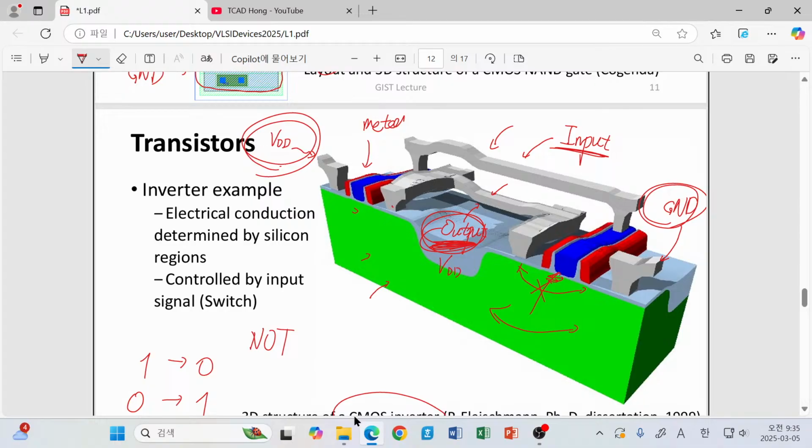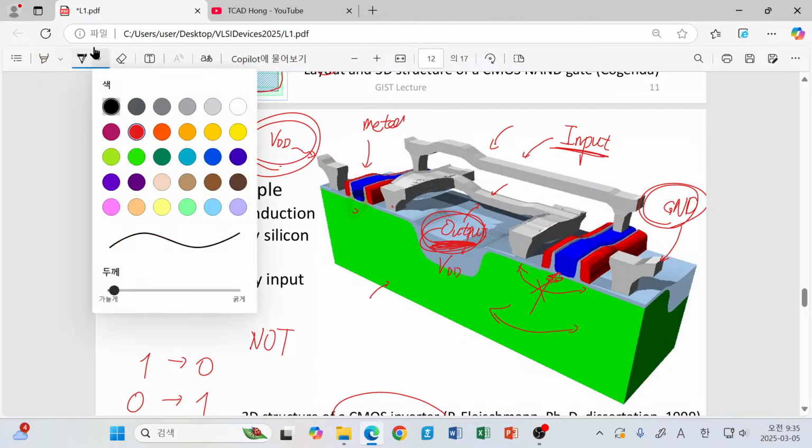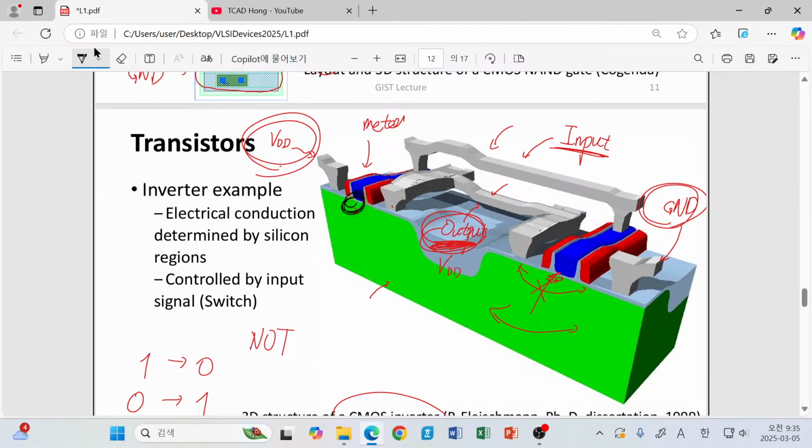The most important part is, we can only say, here, here and here, because by changing the electrical conductivity at these 2 points, we just connect or disconnect our output node to VDD or ground. So although we have a certain system called a semiconductor chip, the most important part is just underneath the gate metal.